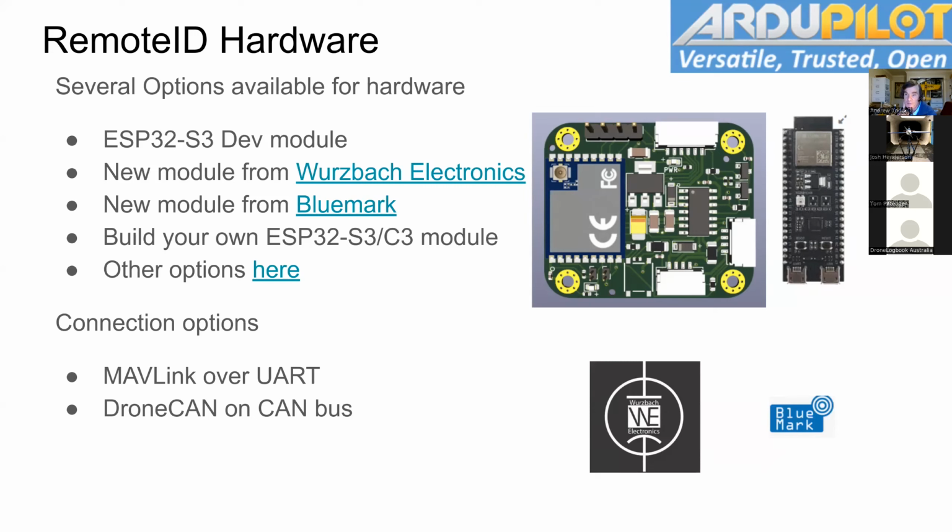But Jeff and I have been discussing ways of using a phone, because compliance testing, strangely enough by the Forestry Service, showed that current model mobile phones later than 2019 are basically deemed to be compliant as far as the accuracy is concerned, because there are accuracy requirements for the positioning of the operator. And so a solution where you have an app running on your mobile phone, providing the position and all the information through to the flight controller, is likely to be viable.